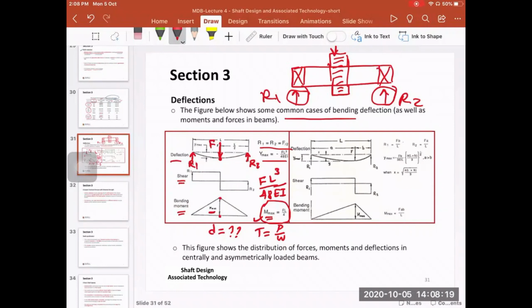And based on the yield strength that can be found from the previous table, based on the factor of safety that could be considered as 2 for general applications, we can find either the diameter, or we can find the factor of safety if you don't want to assume it. But remember that the factor of safety has to be always greater than 1 when you calculate it.